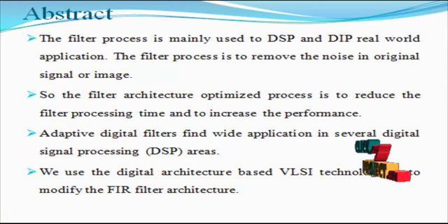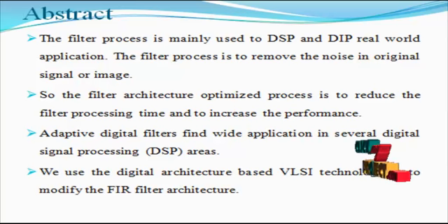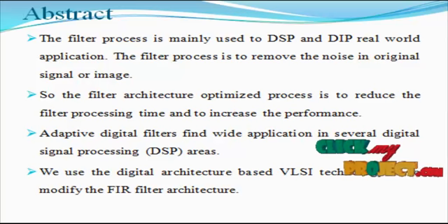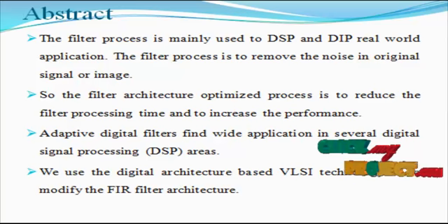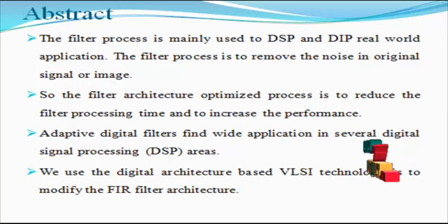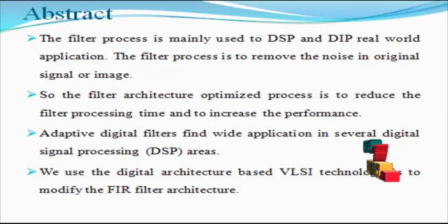Adaptive digital filters find wide application in several digital signal processing areas, for example noise and echo cancellation, system identification, channel estimation, channel equalization, etc. The tapped delay line finite impulse response FIR filter, whose weights are updated by the famous Widrow-Hoff least mean square LMS adaptive algorithm, may be considered the simplest known adaptive filter.